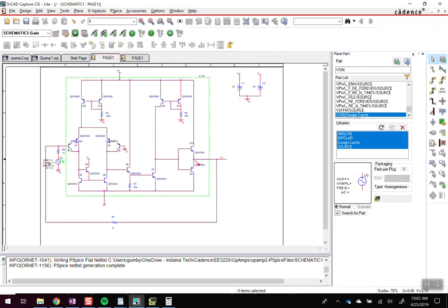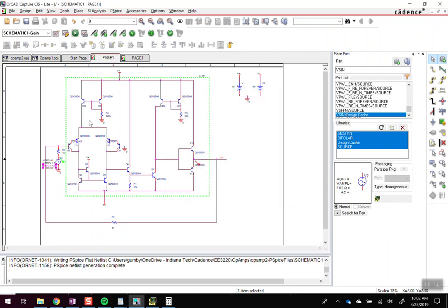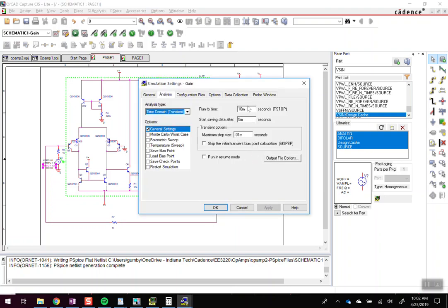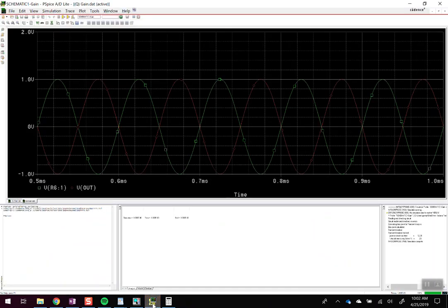Well, what I'm going to do here is increase the frequency. Now, if I increase the frequency, I'm going to have to change my simulation profile. And of course, I'm not patient, so I've opened it twice. But if I've increased the frequency by 10, I should just decrease all those values by 10, and I should get the exact same looking figure. And I do. It doesn't look like there's been anything wrong with it. It still looks the same.